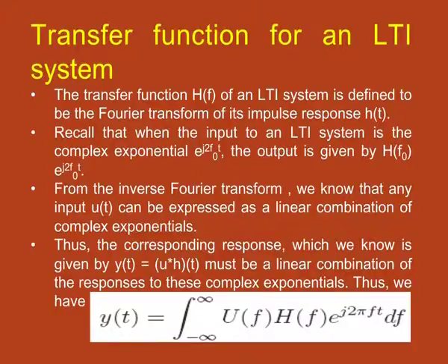What we saw earlier is that when a complex sinusoid signal passes through an LTI system, the output is given by a complex scalar times the sinusoid function of the same frequency. Using this concept, now we will define the transfer function of an LTI system.